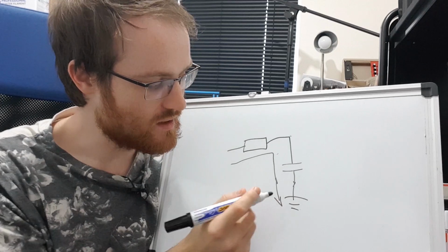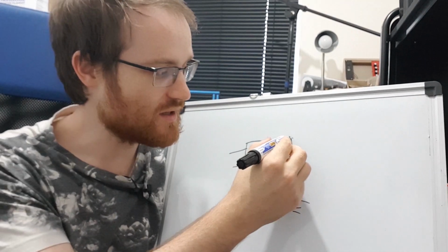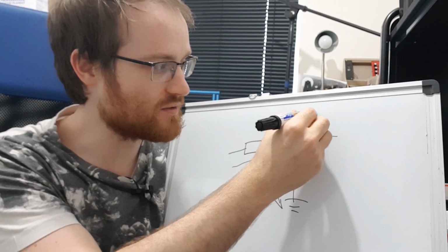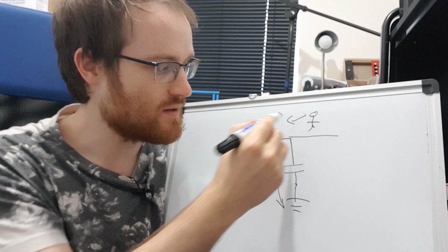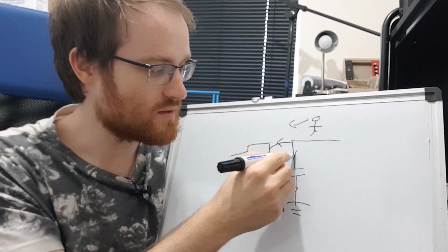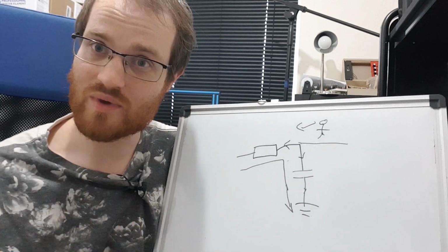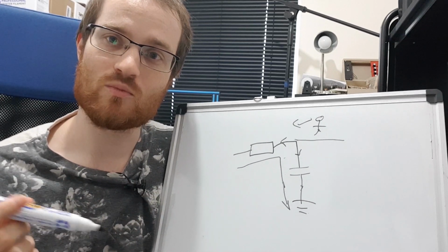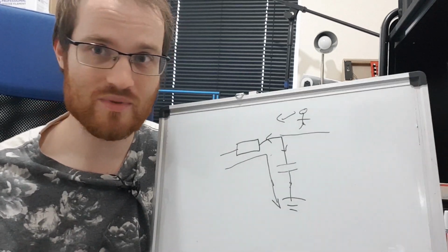So when we say how bad can the output impedance get, we mean how high can it get. So now we're looking this way, right, little circuit dude, we're looking this way, so now we see we've got two paths, and when you see you've got two paths, right, you know that you're in parallel. So what's the highest, sorry, that a parallel impedance can get?